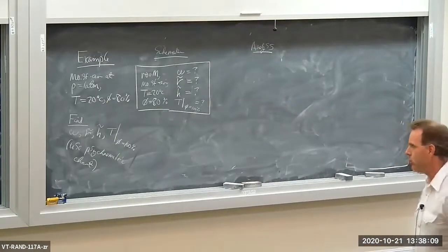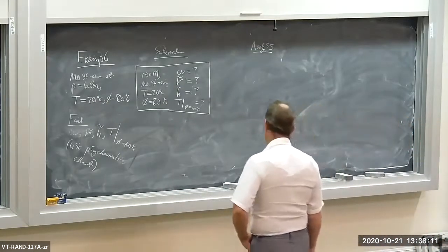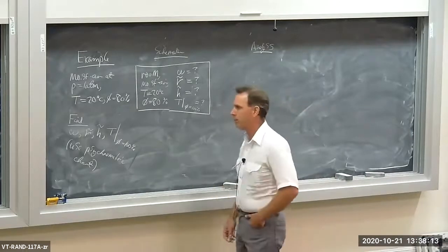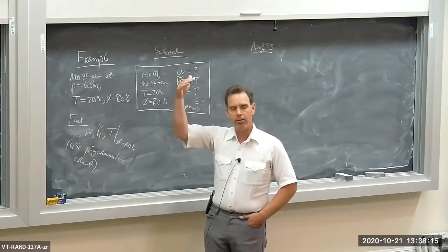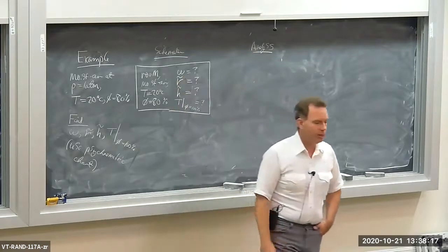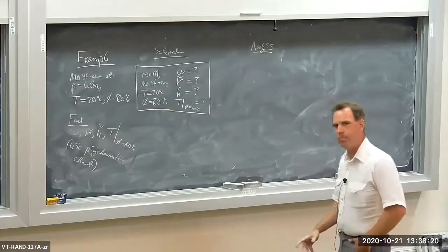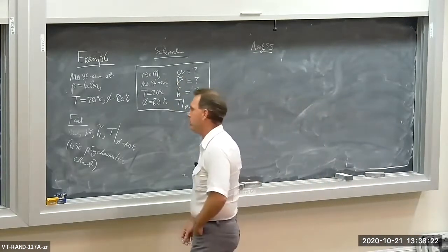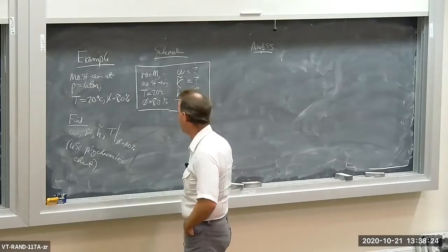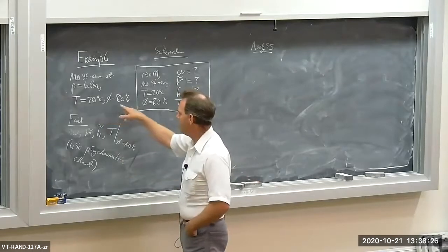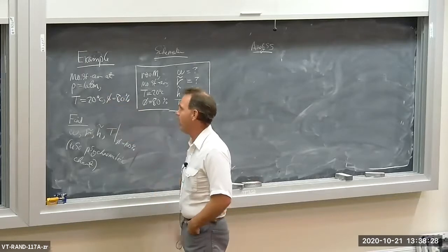Depending on the psychrometric chart, it should typically be for 1 atmosphere, but there are psychrometric charts made for higher elevations or under different pressure conditions, and that modifies slightly the values you get off the psychrometric chart for the various properties. Okay, so we have temperature, we have relative humidity, we know we're at 1 atmosphere.